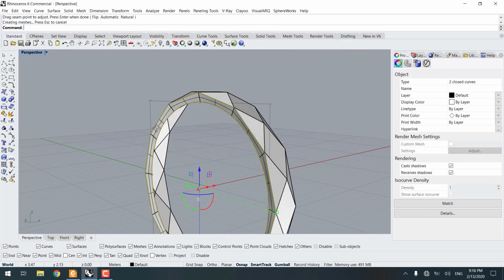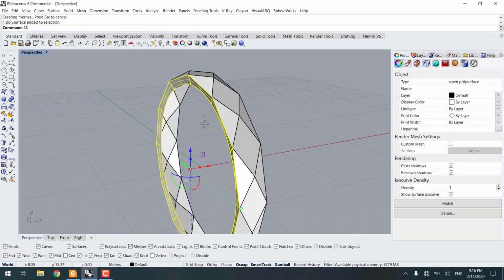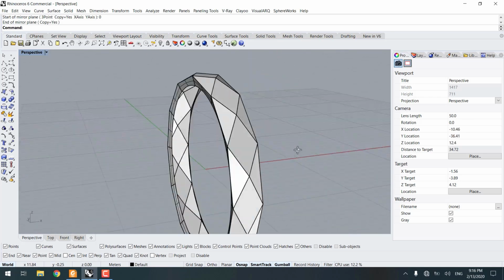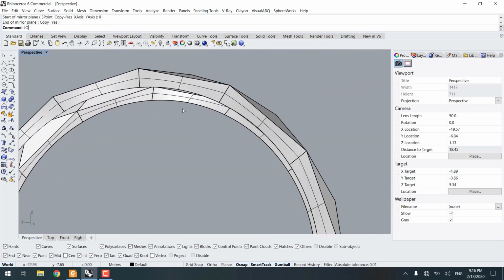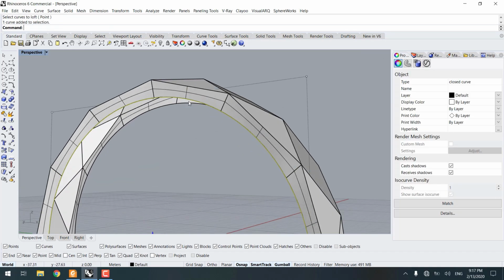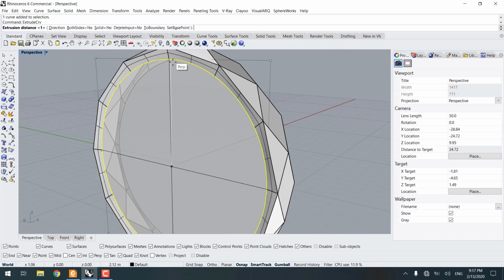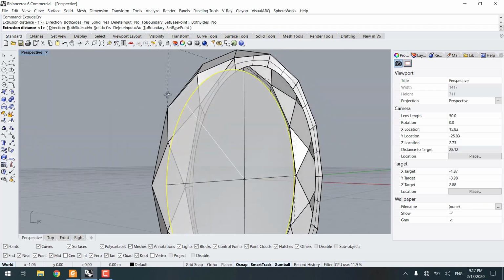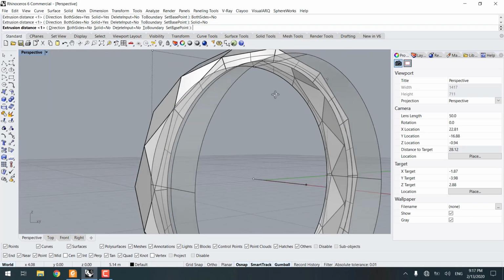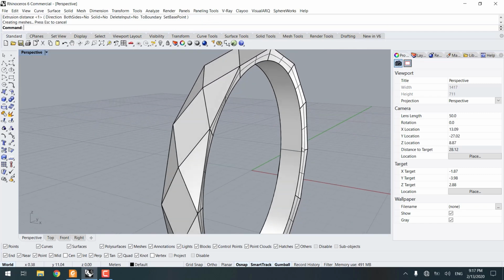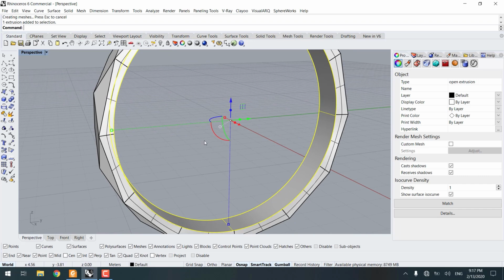Then we need to create a loft using this line and our circle. Just like this. Now we need to mirror this to have an exact symmetrization on the other side. Then again, we need to activate loft, select the circle, and also the other circle that we have on the other side. Well, you know what? Let's do something else. Let's use extrude. Both sides deactivated, as well as solid, in order to create the extrusion that we want.